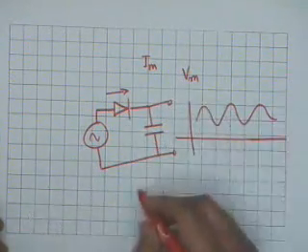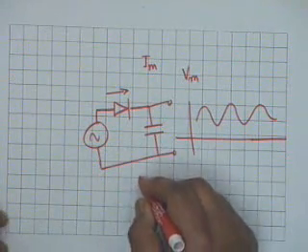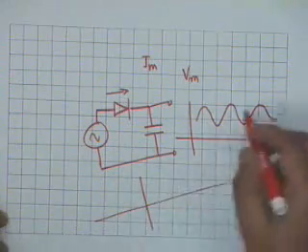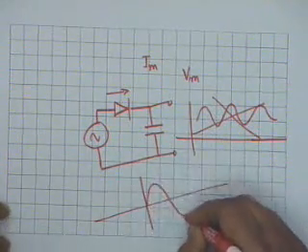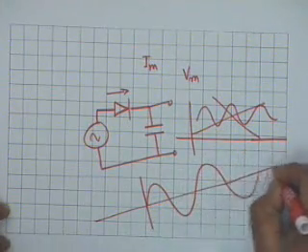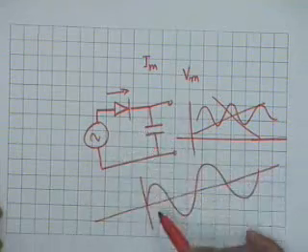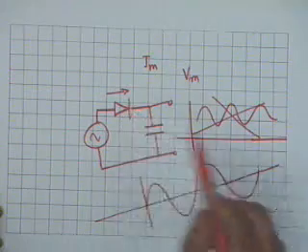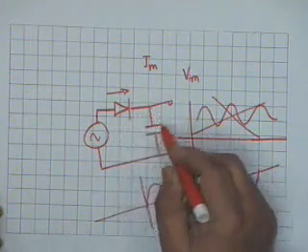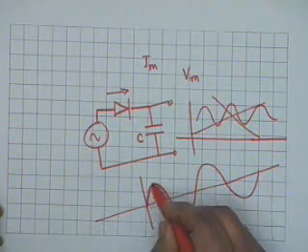So what happens is, if this is a periodic waveform, then during the positive, well, not this, let's take an AC. Once again, what we are going to say is applicable to an AC in which the average value is 0. During the positive half cycle, this diode conducts. The diode conducts and the capacitor C charges, till the voltage reaches this point.